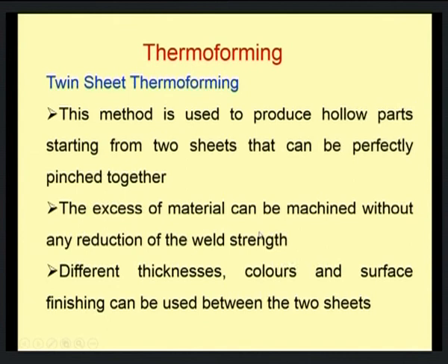The weld strength is this: wherever the plastic sheets join, the mechanical or tensile strength at that point would be reduced. That is what we mean by weld strength, and no such weld strength phenomenon would occur in twin sheet thermoforming. So, this is again an advantage, and different thicknesses and different colors are possible,